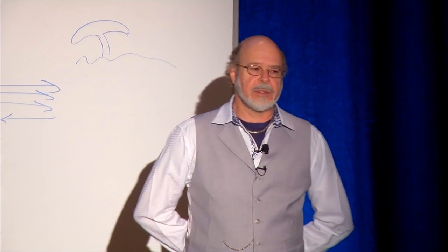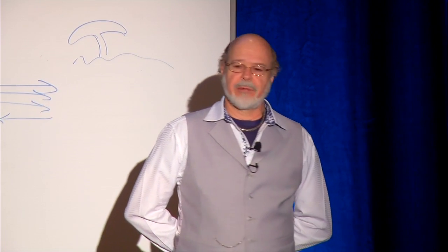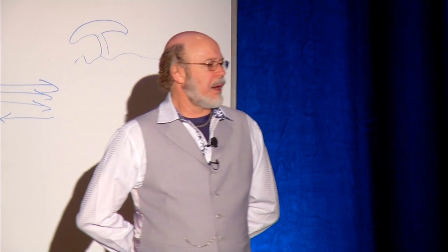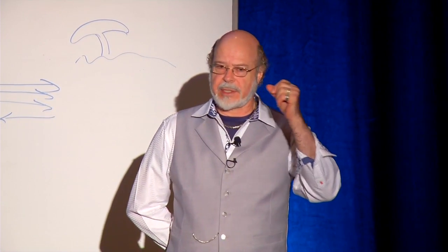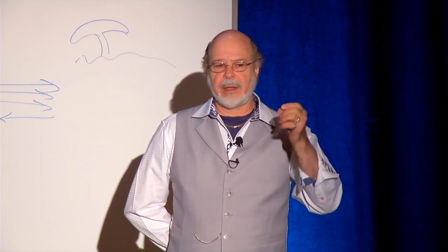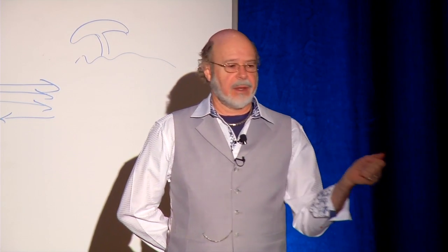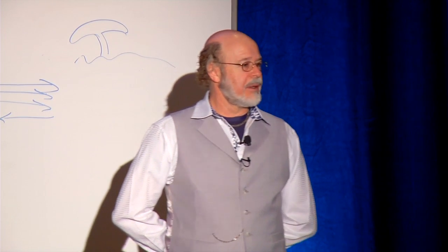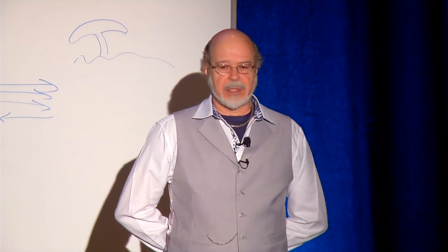I still use the MasterFormat organization as opposed to UniFormat. A lot of people have moved over to UniFormat, but I don't do that. I have a little thing that describes in general what's happening for the whole division, and then highlights that are 50 words, 3 lines or less about tile, unless I need to go on and on about tile. Just the basic things.